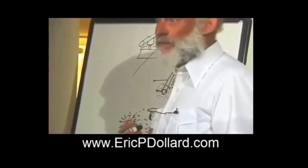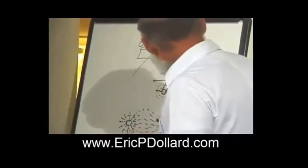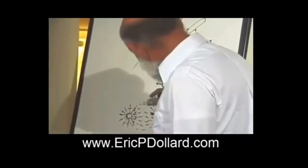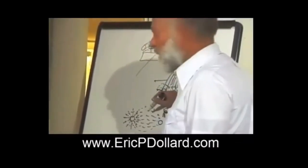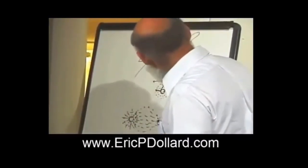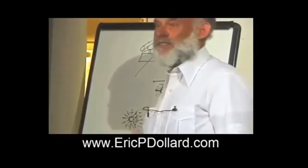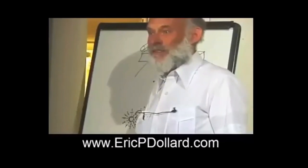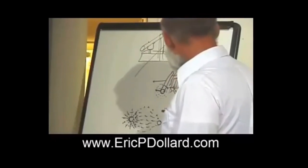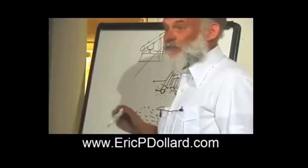Not push them apart, but pull them together. So the force is opposite. Now, if I move the wires closer together, these electrostatic lines of force, or dielectric lines of force, become even more concentrated. So now that I've moved this section of transmission line, the wires close together, the closer the wires are together, the more electrostatic energy the system will store. And it tends to pull itself together, where in the magnetic, the more magnetism there is, the more it wants to push the wires apart and make itself bigger to store the energy.